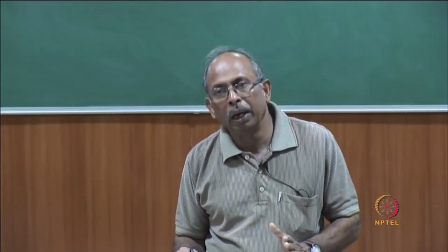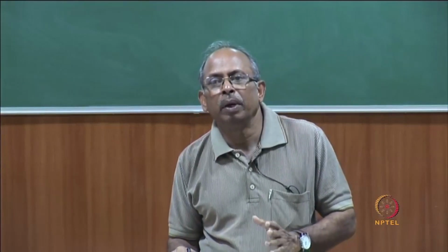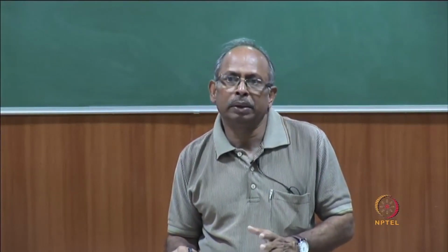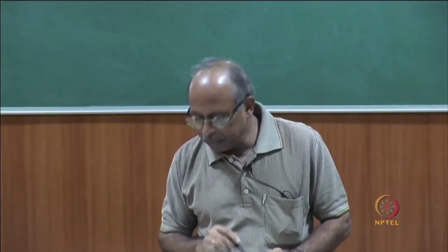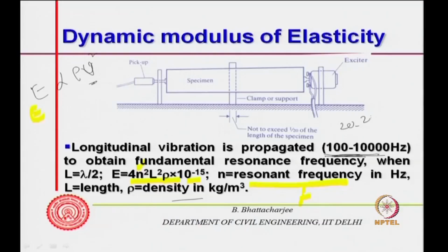First, what you do is you impart longitudinal vibration or mechanical wave, so excite through acoustic waves or sonic waves from 100 to 10,000 hertz, 100 to 10K, all right. So, it is actually sound, because sound is from 20 to 20 kilohertz.